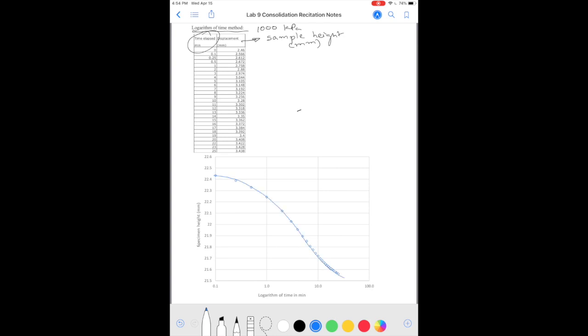Okay. Then we are going to pick any time in the initial flat portion, T1, and multiply it by 4 to get 4 T1. So if this was 0.2, this will be 0.8. So we take that up here, and whatever this vertical distance is, we add that much on top. And that gives us our initial reading at 0. So once we determine what this point is,